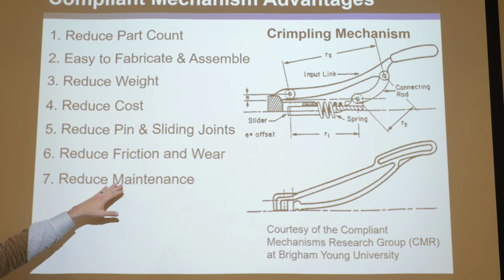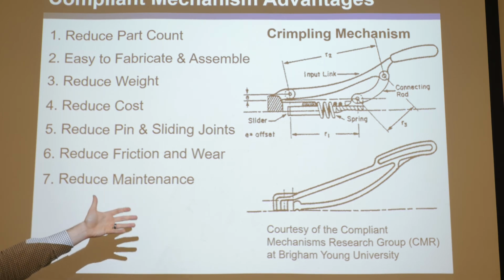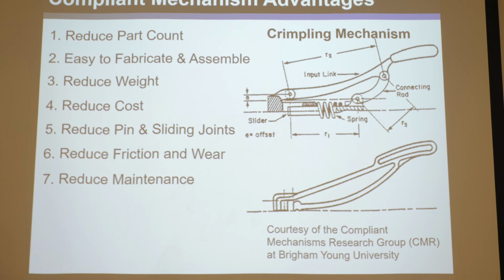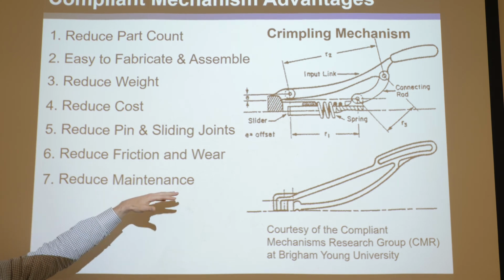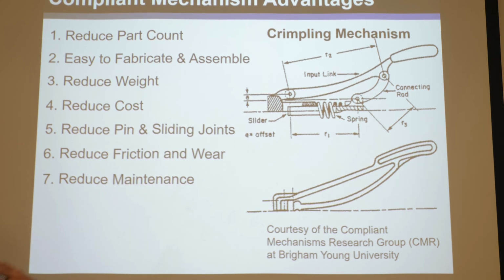Right. So if you have just a single part and something breaks, it's very clear to see where it broke, right? But if you have many different parts, and maybe they're generating particulates, one part's getting jammed, it can be difficult to see, and it can be difficult to fix and replace and everything. So this becomes particularly clear when you try and find something that has the same precision capabilities as a compliant mechanism, which I'm going to talk about a little bit later.